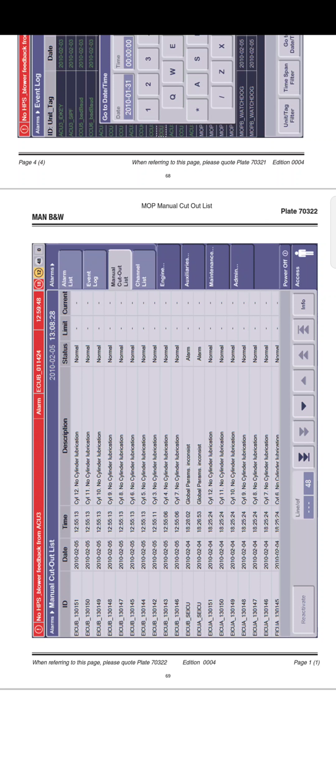Now automatic cutout may be used to suppress alarms which are unimportant in specific states, when the engine is stopped or when a sensor is detected as being faulty. Manually cut out alarms are shown in a separate list which can be accessed from the navigation bar. The manual cutout list we can also see in the topmost position in the right hand corner.